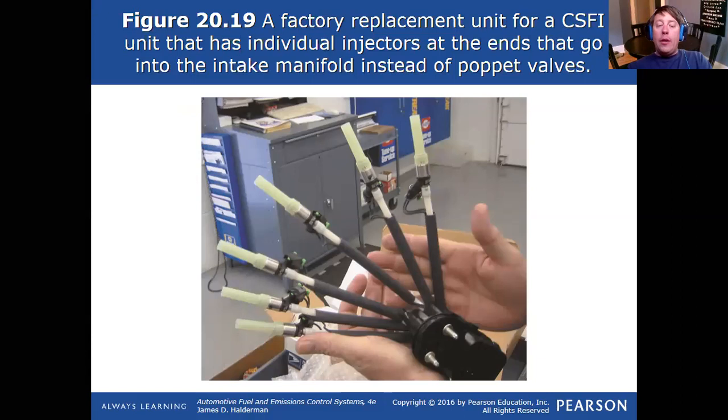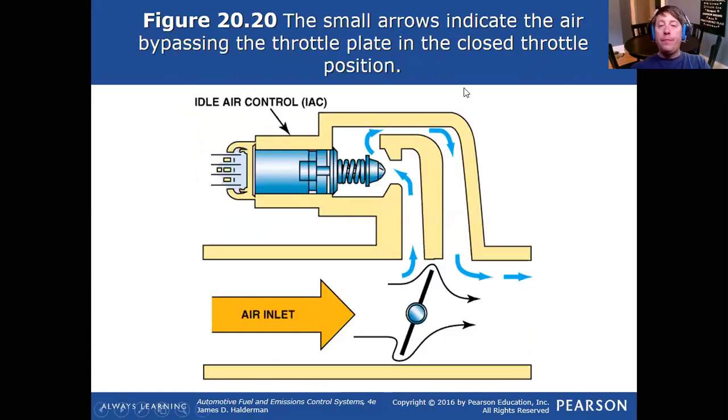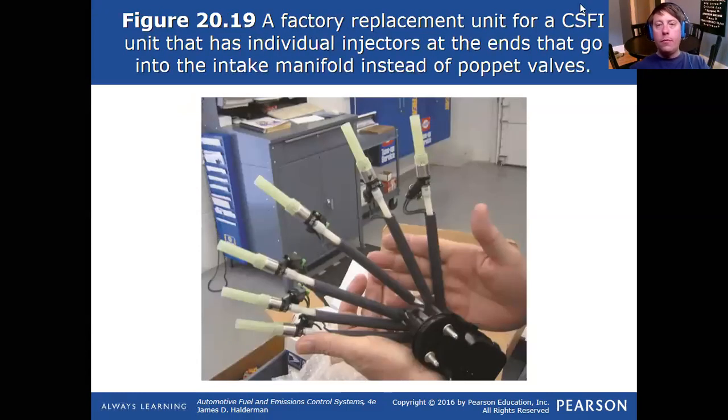what's going on here is you basically have like a distributor in the center of this system, a distributor style, in theory, fuel pump. It's not even a fuel pump, but it rotates, and let's call this cylinder number one. When cylinder number one needs fuel, it's lined up and allowing fuel to spray down this line, and then it allows fuel to spray as it rotates down this one, then this one, and at the very end, you have like a poppet style component there.